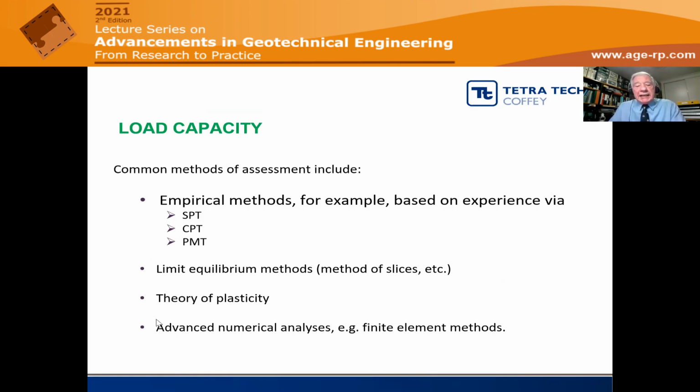Then category 2 methods are limit equilibrium methods, perhaps the method of slices, for example, and the theory of plasticity. The theory of plasticity is soundly based, but quite simplified, because generally we can only handle single or double layers. Finally, we have the category 3 methods, such as finite element methods, which use advanced numerical procedures.